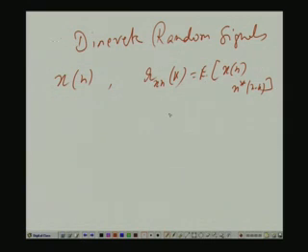So, here the Fourier transform will not be the analog Fourier transform, but the DTFT, discrete time Fourier transform, and that is your phi x x, and instead of writing it as a function of j capital omega, it is a function of j small omega. Small omega is the digital frequency, its unit is just radian. I could have written it as a function of just small omega, but again I follow the convention in DSP. They write the DTFT as a function of e to the power j small omega, though e and j are constants, not variables, only omega is variable, but it is written this way so that you can easily distinguish it from analog Fourier transforms, and also it always reminds us that this DTFT is actually a power series in e to the power j omega.